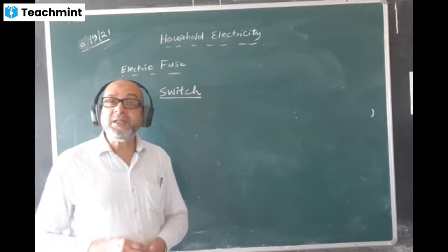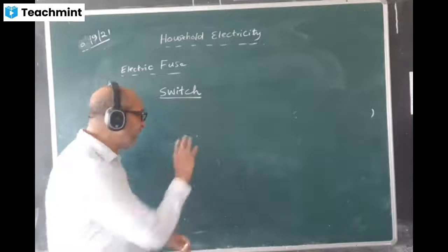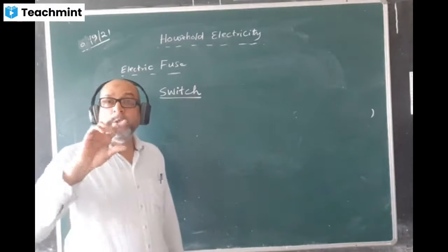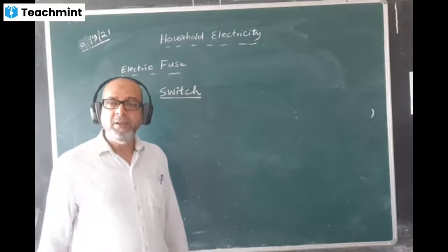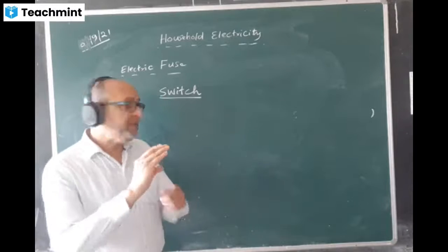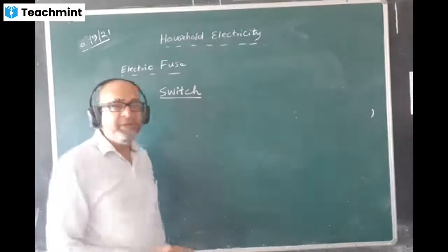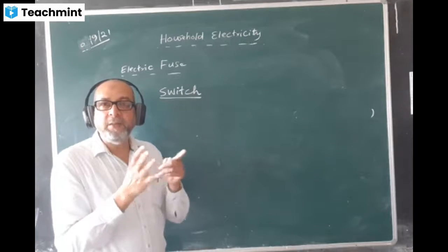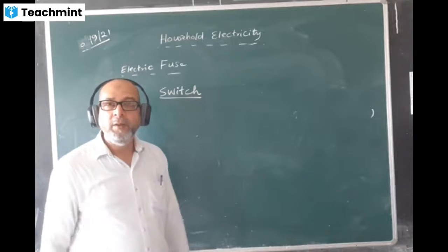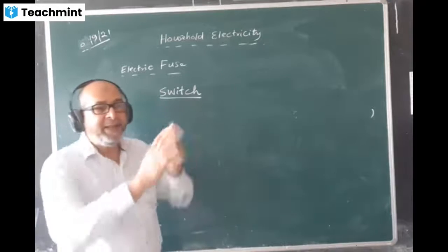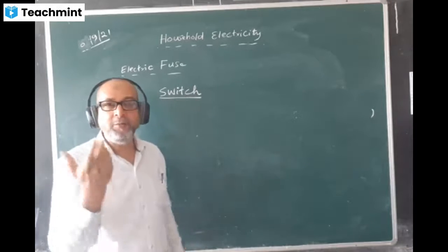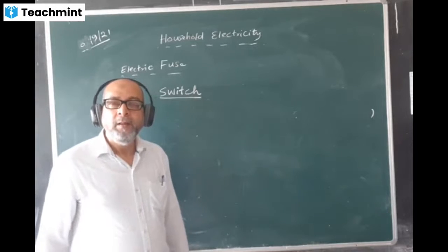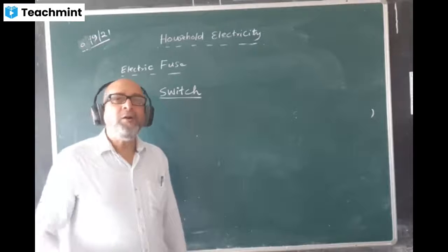Another one, switches must be tightly fitted. There should not be any loose wiring in the switch. Switches must be fitted tightly on the board. Your switch should not be hanging here and there, because there is a chance that mishandling may give you a shock. And you can say, all common sense.